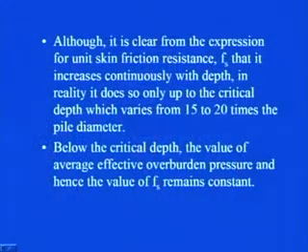Below the critical depth, the value of average effective overburden pressure and hence the value of Fs remain constant, because K is constant throughout the depth and tan delta will also be constant. So, the only thing which was varying with depth was average effective overburden pressure, and beyond critical depth, since this is constant, this Fs is also going to be constant.